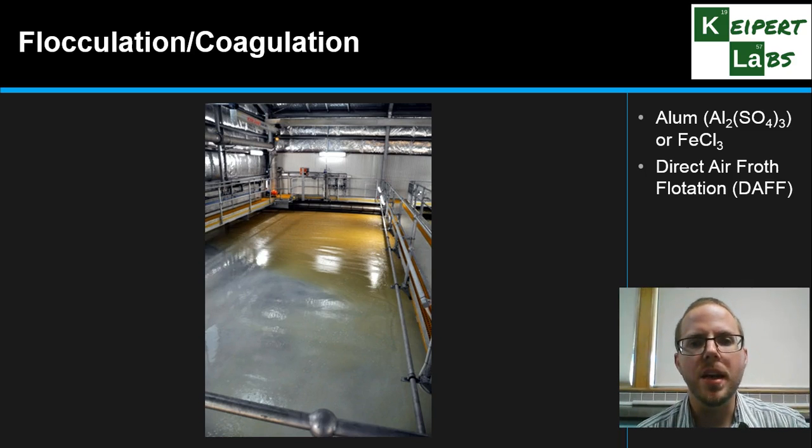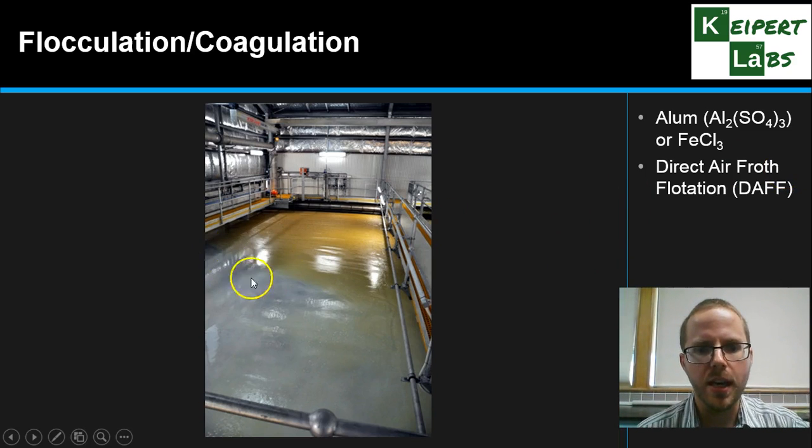In some places that will settle or sediment to the bottom and then is removed from the bottom. But here in Coffs Harbour, we pump air into there. We use bubbles of gas that actually floats that scum to the top where it can be skimmed off. So you can see here that we've got this brown area where there's scum and the clear area here where it has been removed. It's continually scraping it across, I think about every half an hour or so, and that takes that level off. They'll take the clean water from underneath and then follow it on to the next process.